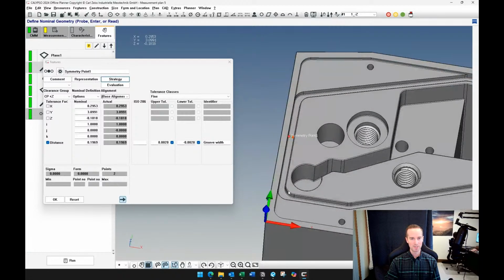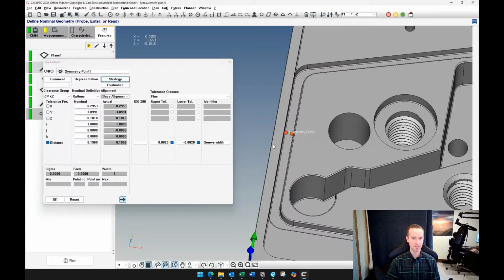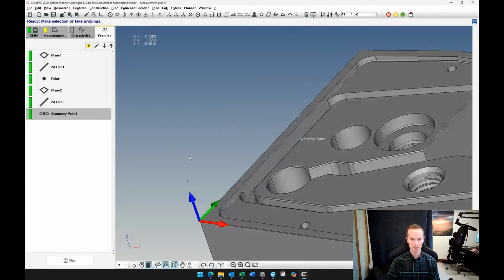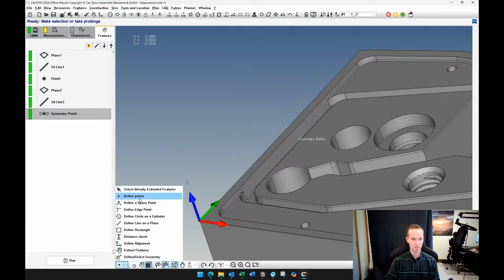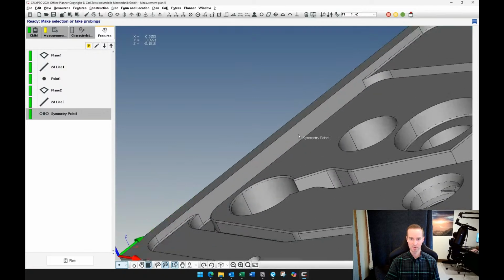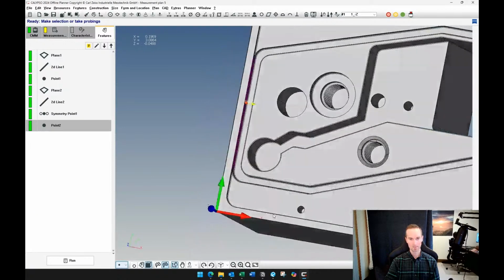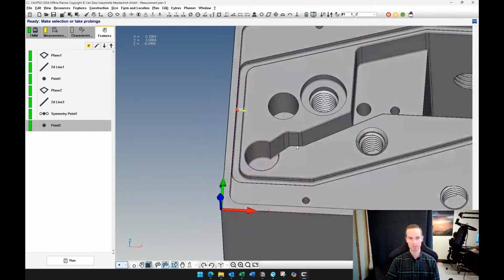What else? When you're dealing with small grooves, there's part variation. Again, similar to the Z origin on the pocket, one thing we might do is set a local XY origin so that the probe can get in there precisely even if the entire groove is shifted. So what I mean by that is we would take a point that is not in the groove, but somewhere near. So let's say we do a point here to set a local X origin, and then somewhere else we might